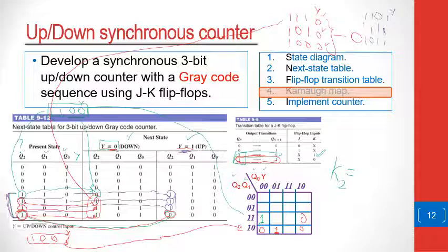So if we plot this on the K map, we see that we have 1101, 1101. It will have to correspond to 0 because all of these transitions are 1 changing to 1. So this will be plotted as zeros. So it's 1101, and then 1111, and then 1011. The rest therefore become don't care.